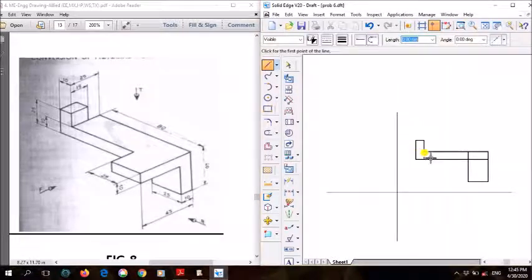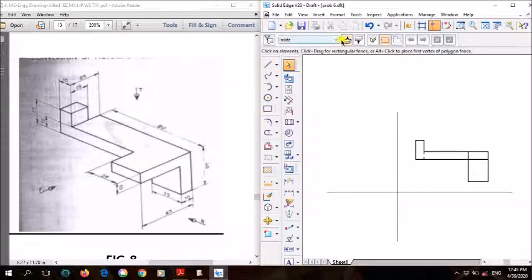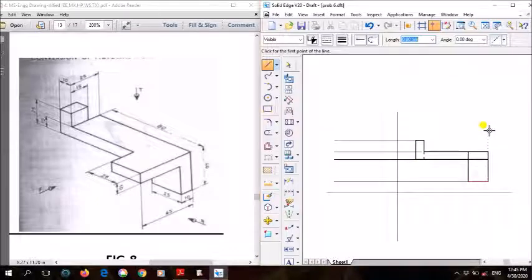Okay. So what we'll do is we'll just project this projection line from all the corners, and automatically we'll get the right view. So here you project this corner from here, straight line. Okay, using thin line. Using thin line, you project this corner. Next, you project this corner. You project this corner, and finally project this corner. Clear? So like this we have projected 4 corners. So now we'll see how the right view looks.